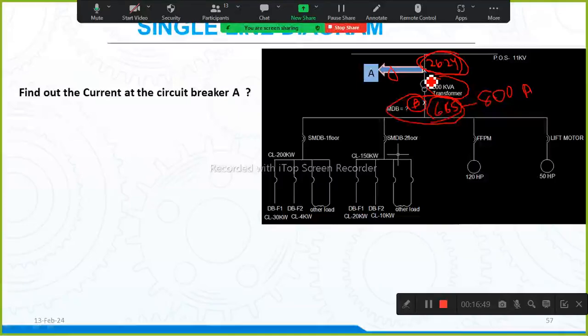Now you might ask, why sir, an MCB can withstand up to 63 amps? Yes. So an MCB can withstand up to 63 amps, but an MCB doesn't have an arc quenching medium. What is arc quenching medium? I'll tell you. Take an example.